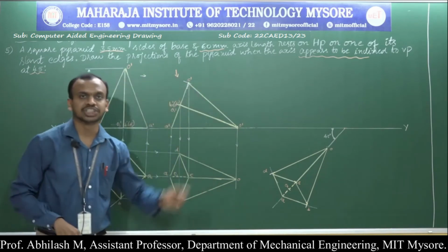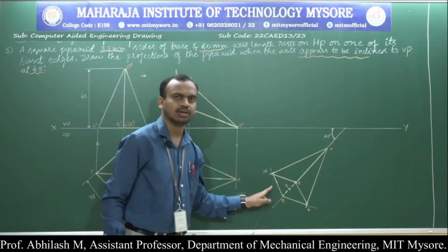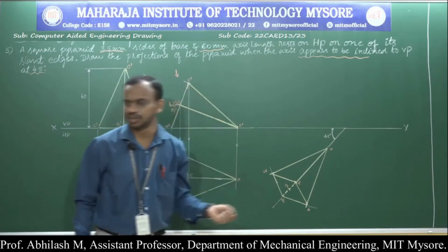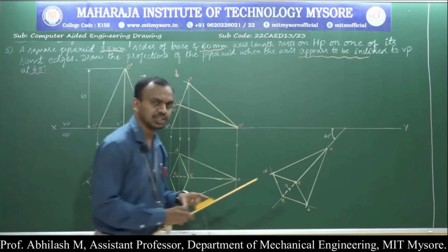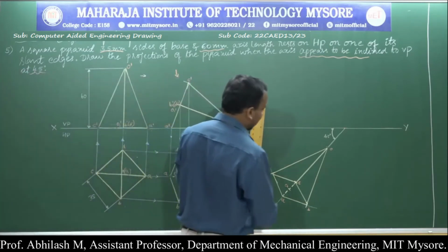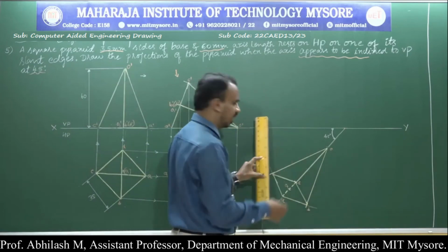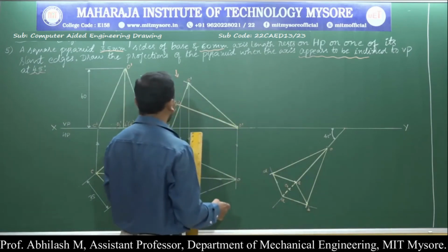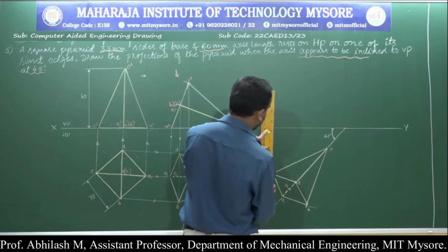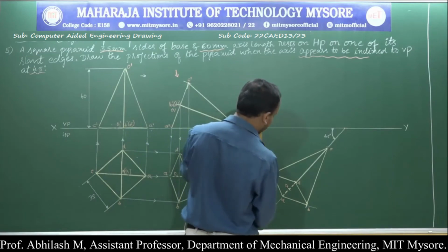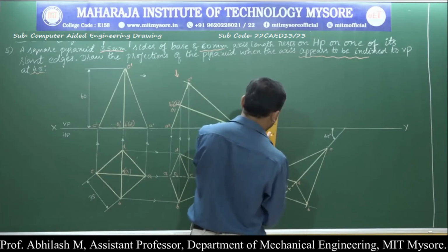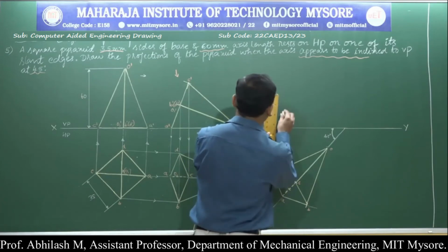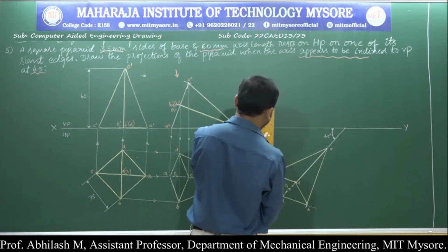In order to finish my final position, I am supposed to draw the projection lines from this particular position. How to draw the projection lines? They are the thin lines that we are supposed to draw. Let us begin from each of the points and we will complete the position. But ensure that while drawing the projection lines, you don't exceed the lines. Okay. So we will begin from our point D. So D approximately comes over here.